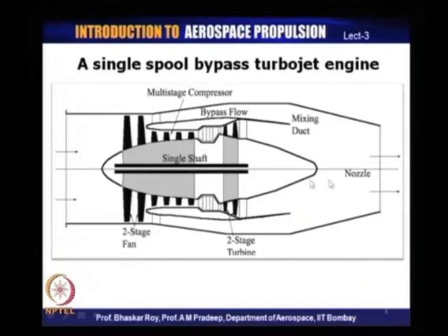it had been a pure jet engine, which would have had a higher exhaust velocity, which means it would have had a higher temperature and higher kinetic energy at the exit, and as I mentioned, this higher kinetic energy would have been a complete loss.